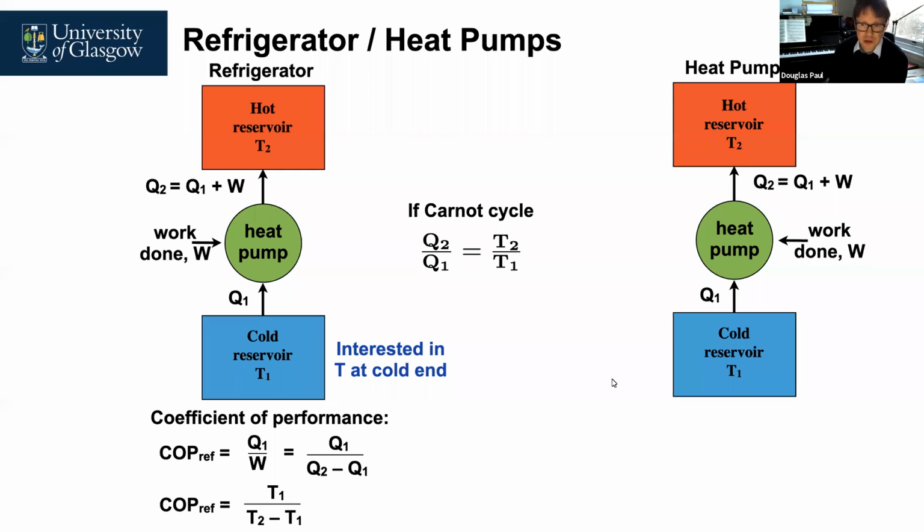So the point about the Clausius statement is that if there is no work done, heat will flow from the hot reservoir to the cold reservoir. But if we do work with a heat pump, then because we're putting energy in, while it's costing us energy to do that, we can transfer heat from a cold to a hotter body.